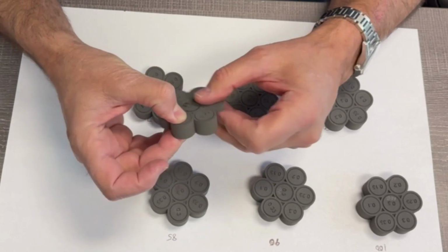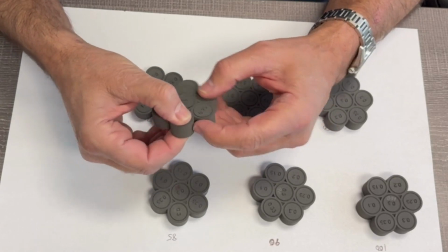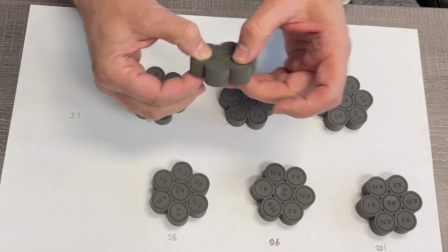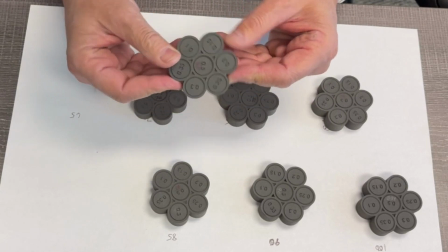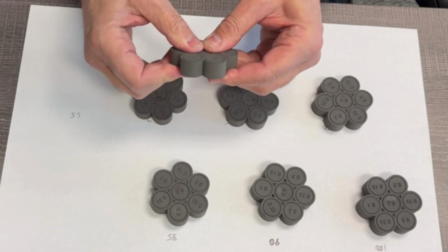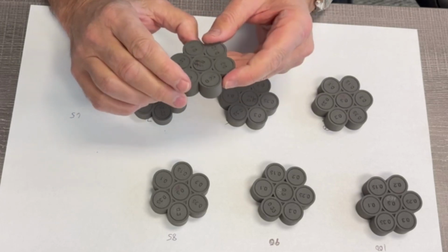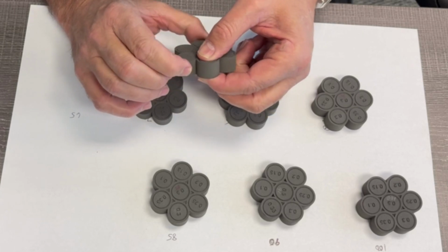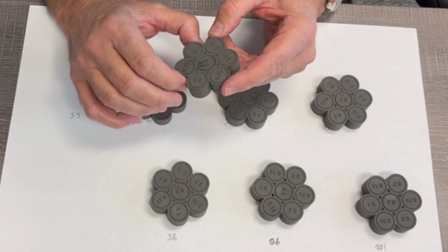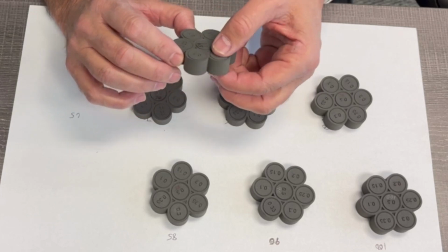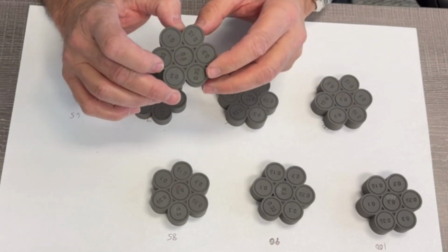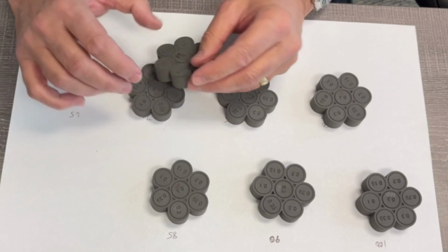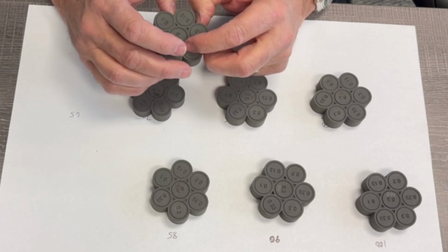In fact, the 0.3 moved very easily. I said moderate, and I actually got the 0.25 to move. I mean, it actually moves pretty good. So overall, printing at 65% of the energy density, I was able to get all the way down to a 0.25, where 0.3 was moving pretty good. We don't need to be at 0.25 in terms of designing, but it was just kind of good to know maybe I could go lower if I needed to in my energy densities.